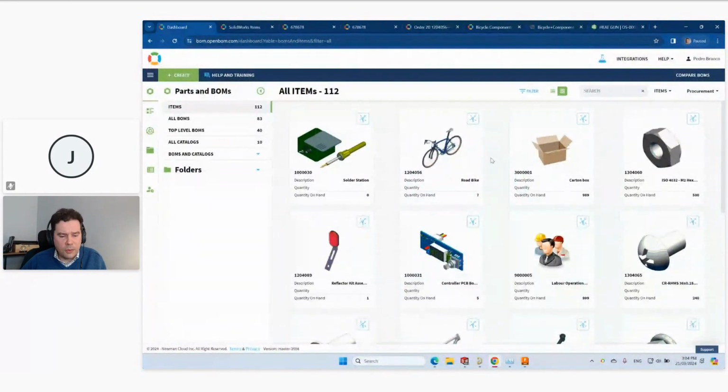The difference between a product structure and a bill of materials is that the product structure could have your complete intellectual property, your complete levels from all levels. Even if you have contract manufacturers, you might want to capture what the contract manufacturer is building into drawings and materials. So you have complete structures versus manufacturing BOMs, for example. They are a lot more focused on materials levels, what you actually buy to assemble in house. But let's go through and see different CAD systems and how you can extract data from them.